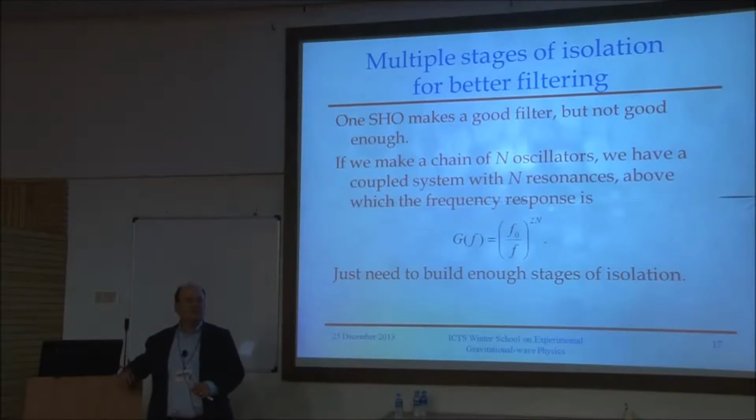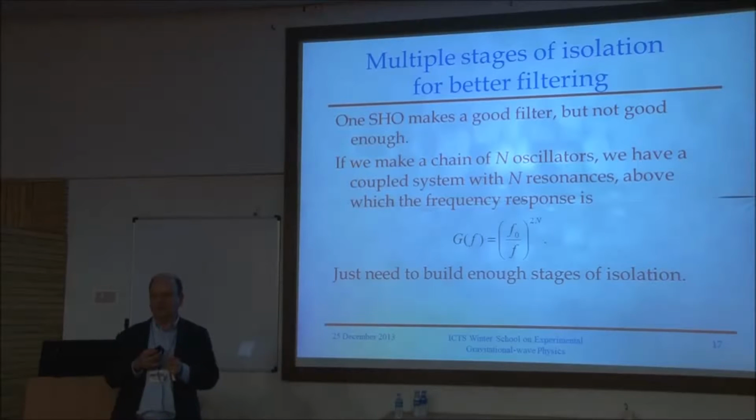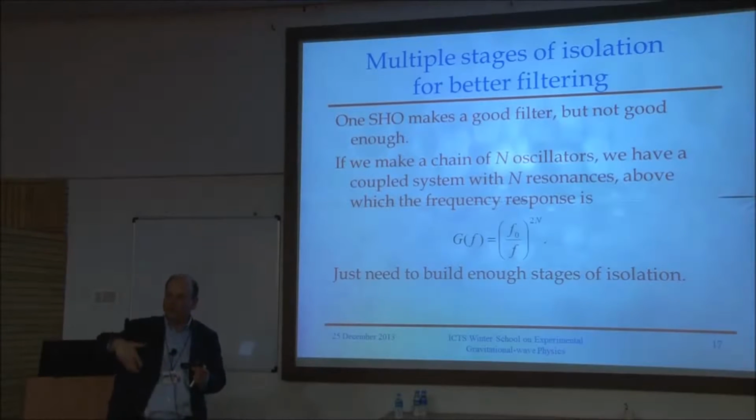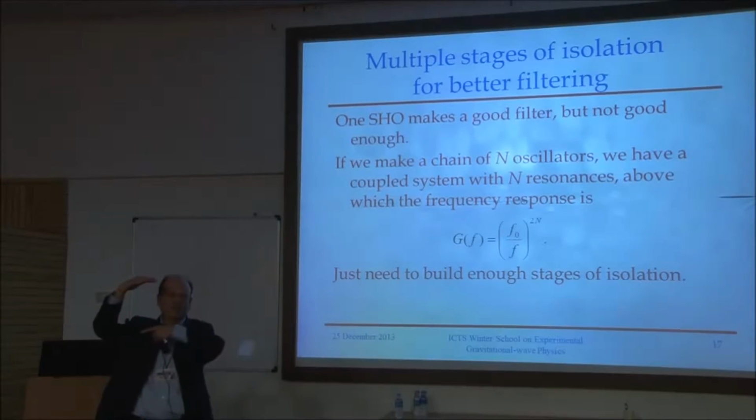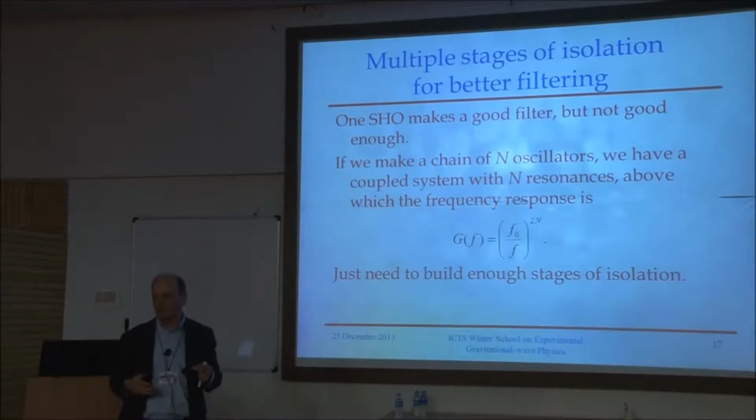If you make springs in a dumb way, that is the way I kept inventing them over and over, there's an interesting theorem that tells you a limit on simple-minded ways of doing this. For any kind of spring that supports weight, and stretches, like the coil springs I will show you, or any other elastic thing that deforms downward under the load, the stretch of the spring when you load it is equal to the length of an equivalent pendulum that has the same resonant frequency. So a 1 hertz pendulum is the better part of a meter. If I want to make an ordinary kind of passive isolation thing, it deforms by a meter, close to a meter, when I load it.